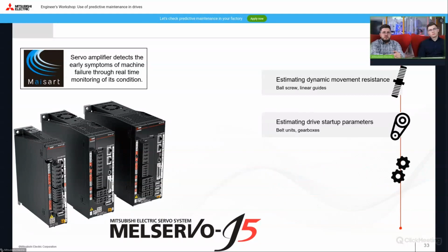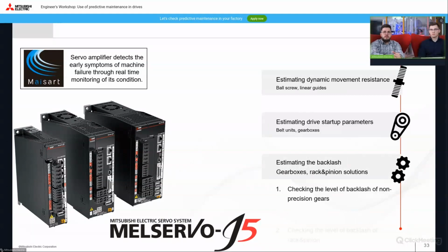And last but not least, the gear backlash measurement application. Unfortunately, this can work only with our software and only in service mode due to the characteristics of the tests, and it only allows gear backlash to be checked for low precision systems. Yes. That means for planetary gearboxes, it doesn't work correctly. Yes, in our software, as Adam showed.